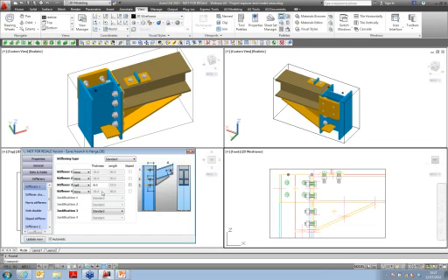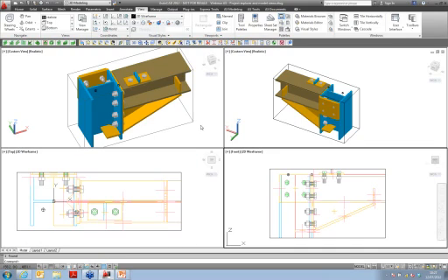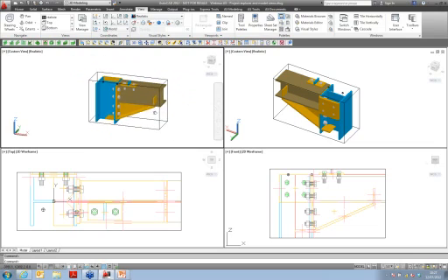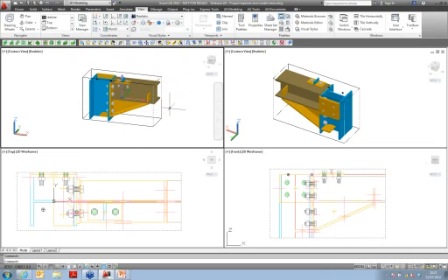I can ask also for stiffener number 4, half or full, and I get the result in real time. I can even specify a specific thickness for these stiffeners. So I get the result. It's very efficient, you see, to work with 4 viewports, okay, and you can even rotate the view to see the result.